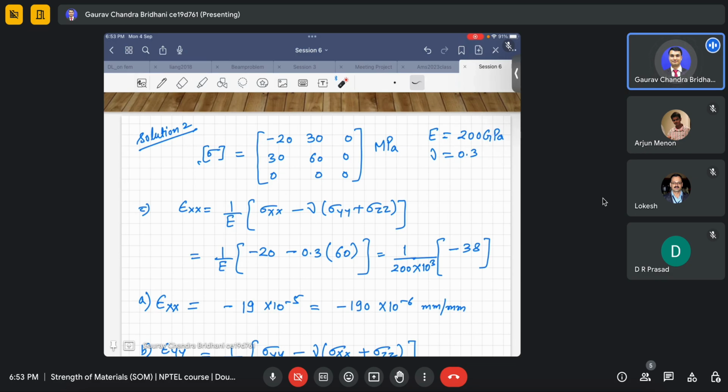They actually happen on the plane where you have more shear, 45 degrees. When we apply uniaxial tension, a plane whose direction is similar to the direction of the loading doesn't fail in ductile materials, but it fails at 45 degrees from that plane. That means it fails on the plane where the shears are higher, and we will see this later in the failure theories.